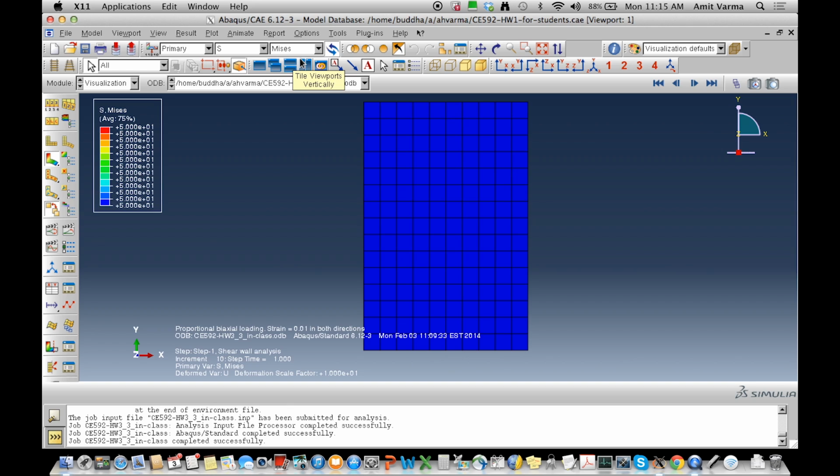It tells you the square root of 3 multiplied by J2. It tells you what the effective stress is. It just calls it the von Mises stress. And if your von Mises stress is greater than 50 ksi for an elastic, perfectly plastic material, you should run out of the room. Because it's not possible for plastic. That means that that software is pulling a fast one. Right? It's trying to tell you something that is impossible.